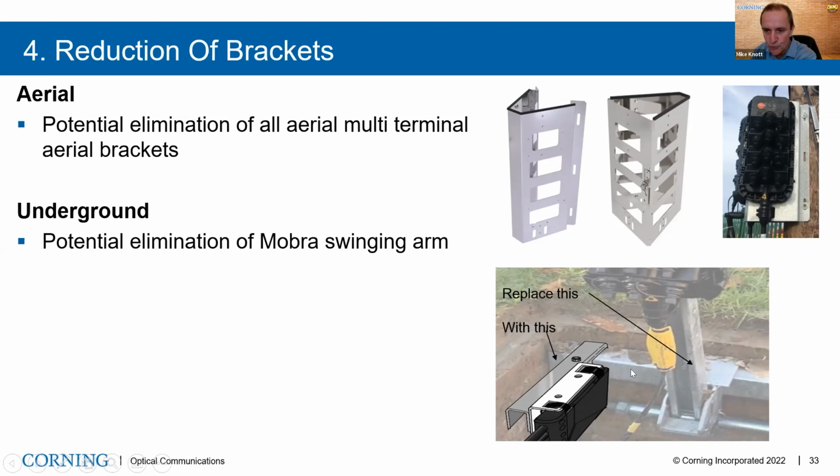Openreach have this no drill frame, which is mounted inside the chamber, a kind of expansion device, which means you don't have to drill the walls of the chamber. And we have this very simple metal bracket, which fixes onto their existing no drill frame, and you just hang the terminal from there. So it's much simpler, much less space, much cheaper.